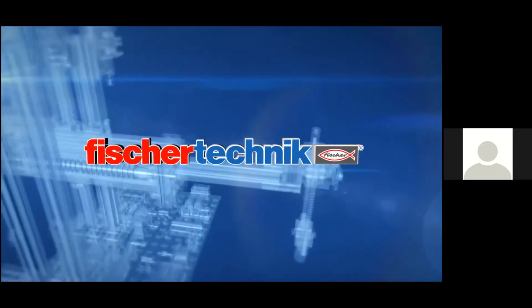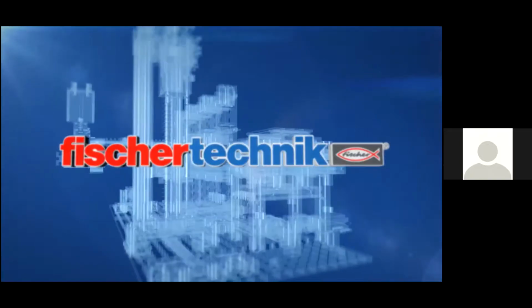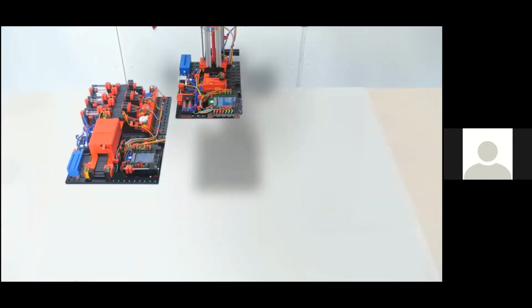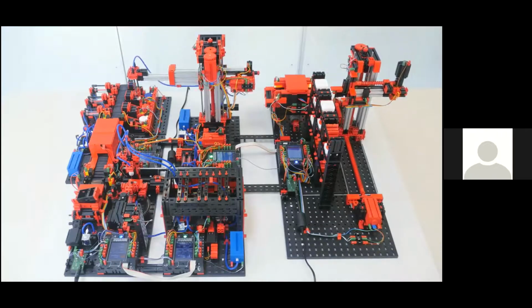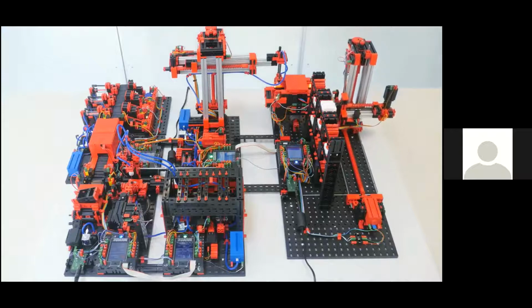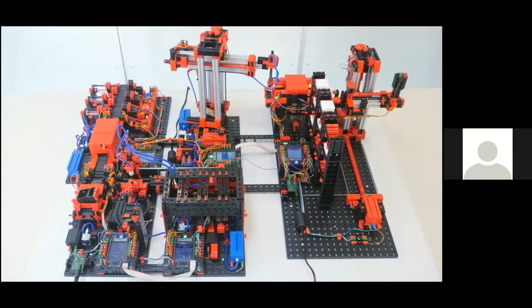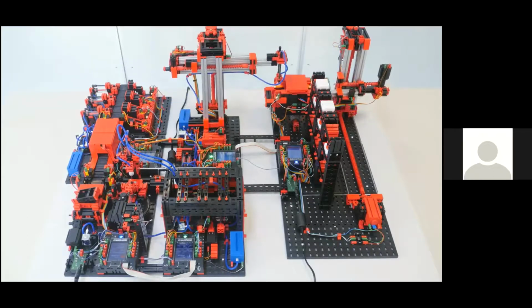The cycle you're going to see works like this. Work pieces are retrieved from the automated high bay warehouse using the vacuum gripper robot, and then moved to the multi-processing station with oven. After the work piece has been processed by this machine, it is then sorted by color in the sorting line with color detection, before being again moved by the vacuum gripper robot back to the automated high bay warehouse for storage.